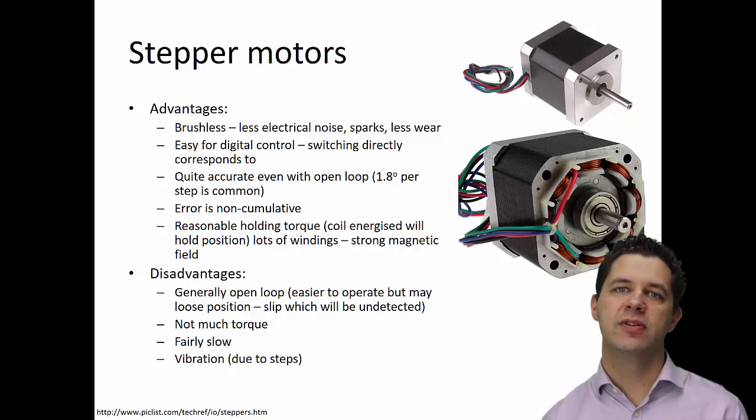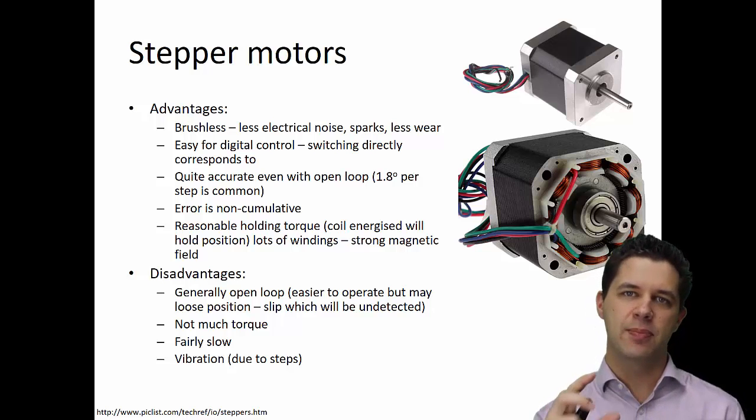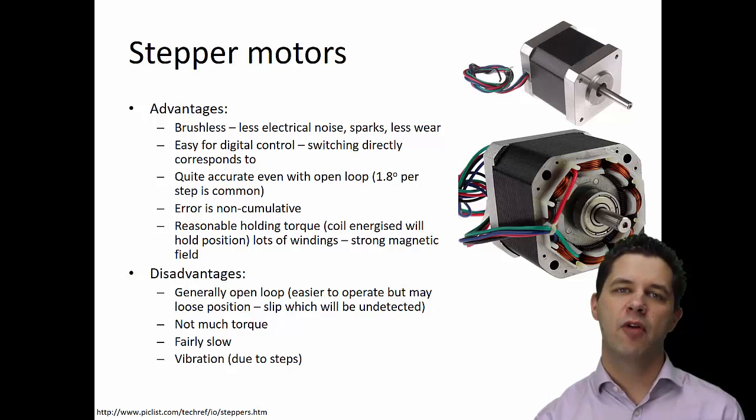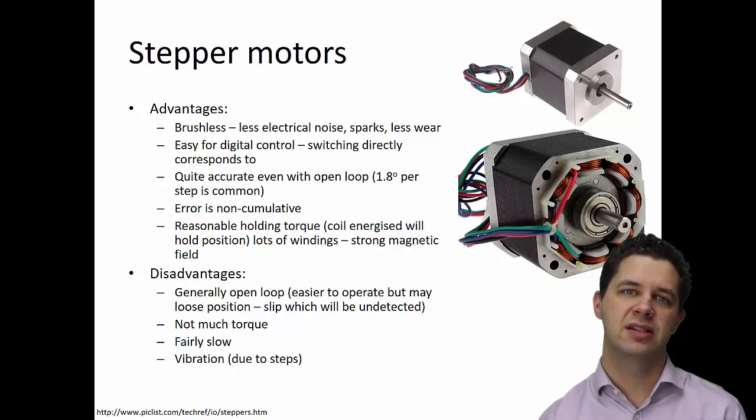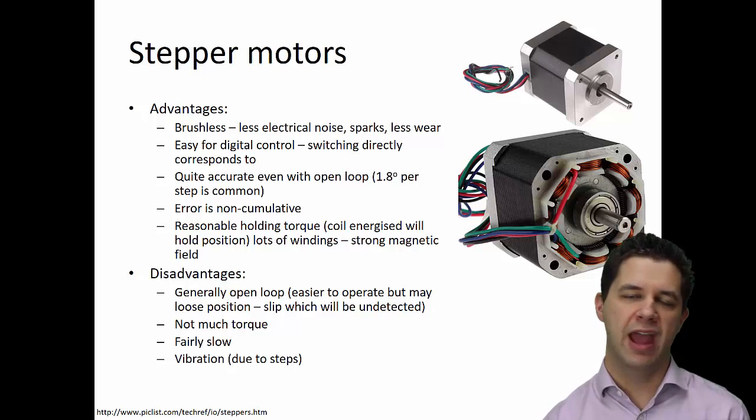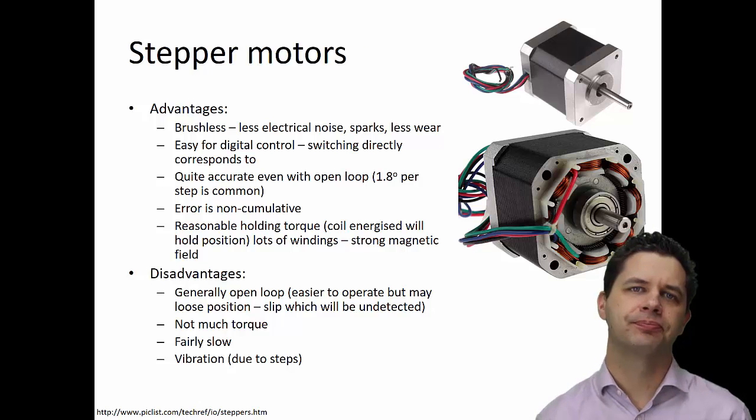They can also induce a bit of vibration to the system, because remember they're stepping a step at a time and then stopping. Vibration can be induced into this system, and we may need to have some decoupling there to try and reduce the vibration that these induce into our frame or into our system that we're driving.